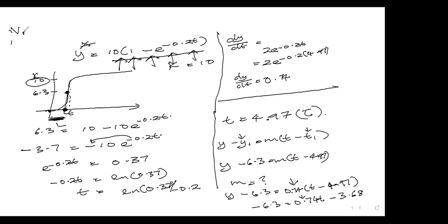Because what is it? V is equal to V naught times (1 minus e to the minus t over CR). Yeah, something like that, yes, sir. So V equals V naught times (1 minus e to the minus 0.02t). So CR, the tau, would have been 1 over this. So that looks right to me.